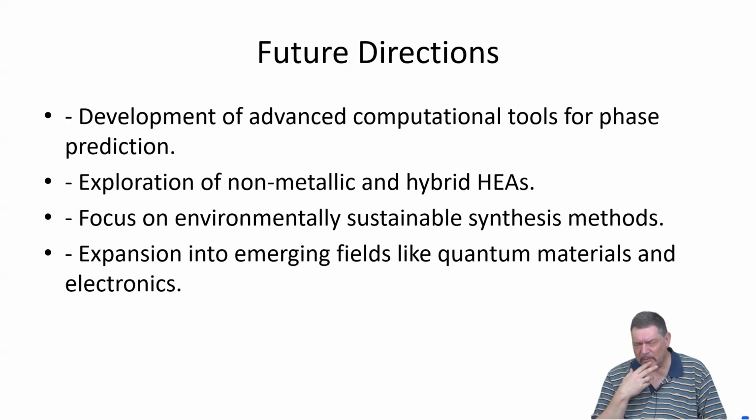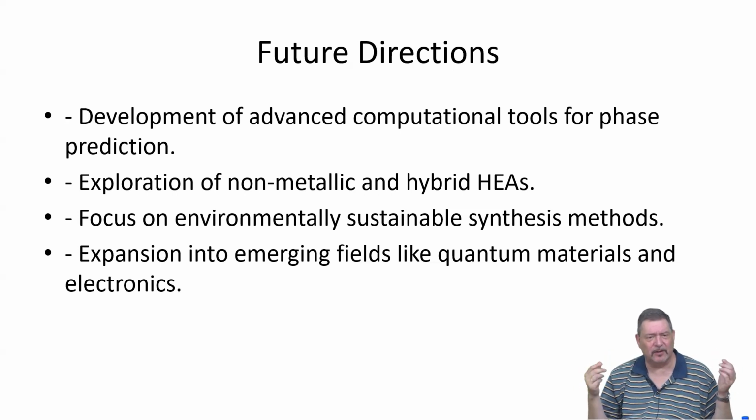And you know, or maybe you don't know, who is doing CALPHAD? From you guys? Okay, nobody. So CALPHAD is excellent at solving large sets of equations, and also differential equations, right? So you get basically a solver, and you put in the data for mixing enthalpies, mixing entropies. That's mostly it. In some refined versions, you also put in some diffusivity data. That's called DICTRA, the module in CALPHAD. So you get also the kinetics of phase transformations as an output.